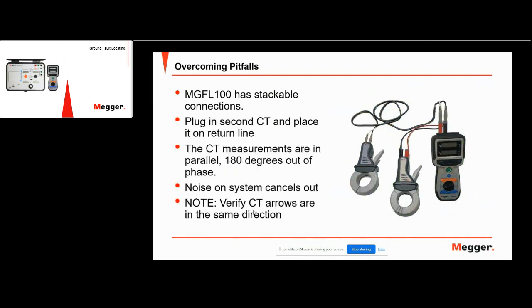And the one thing you always want to do when you're doing this method is make sure that the arrows of the CTs are in the same direction, because they have arrows pointing toward the loads typically.